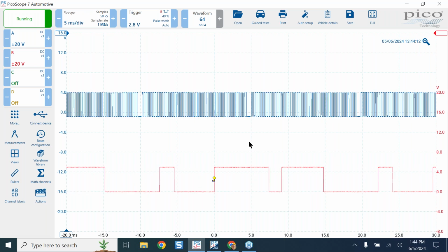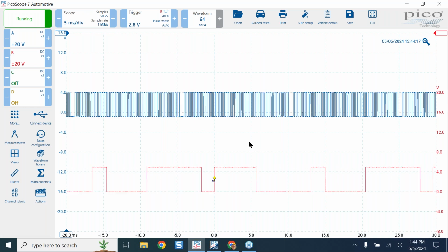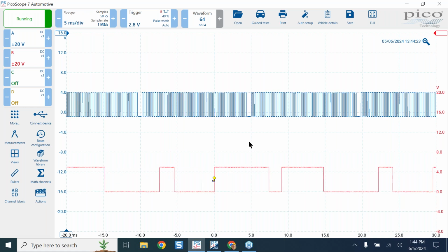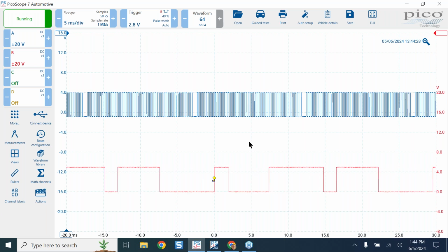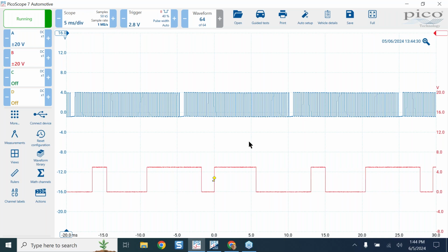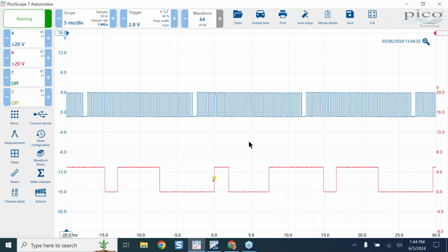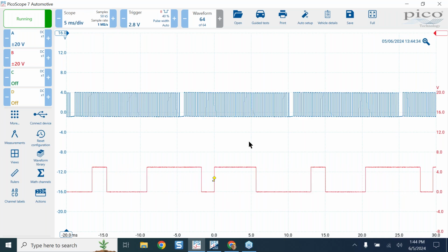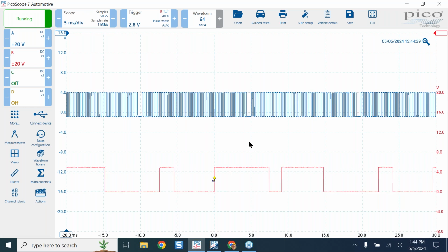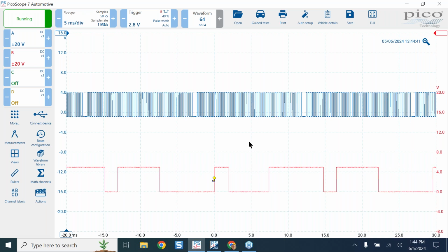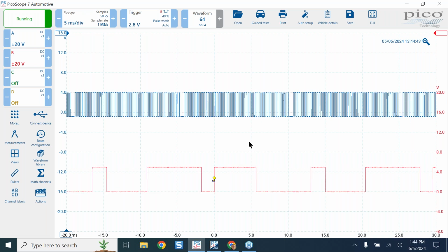But that doesn't improve your skill of using time-based triggers. Even using ignition, the trigger can get not very settled because ignition does bounce around a lot. So it's fine to use COP. It's fine to use a secondary source that you're not analyzing, but I don't think that improves using a time-based trigger, which is really the focus here: to just add another tool to the toolbox. And I think PS7 does a really easy job.